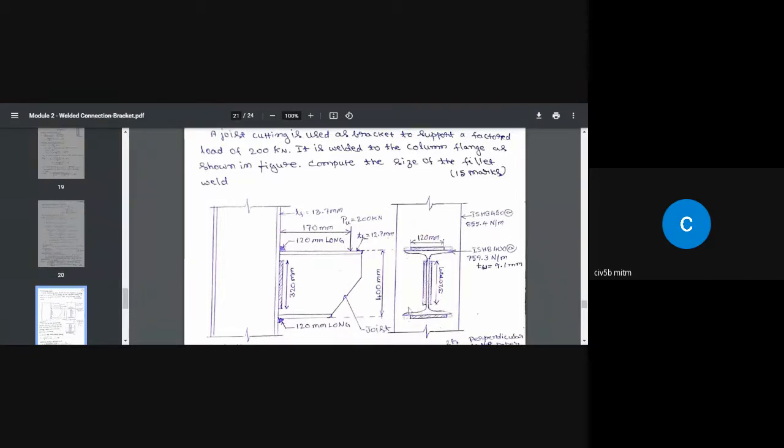So that means total height minus flange thickness minus R1 value, two times of that. Finally, it will give you this height and provide that much of weld. So that way you can fix it, but in this problem it is already given. The R1 value, thickness of the flange and all those things you are going to get in the steel table.